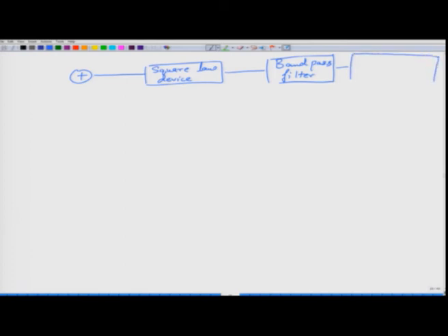It is to increase the power of the amplitude modulated wave so that it can be now transmitted, and the requirement of any repeater or any amplifier is reduced. So, the third element, after passing through an adder and then to a square law device, and then to a band pass filter, generally it is sent to a power amplifier.